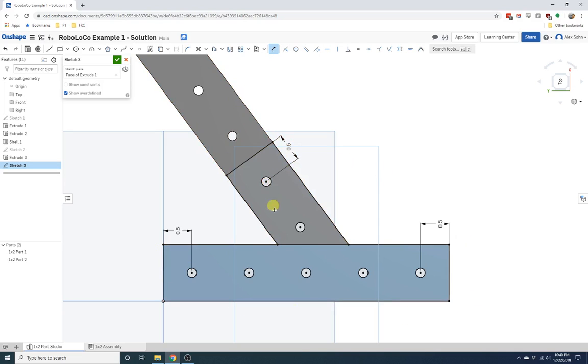So I have all the holes defined that I want to attach everything, and I have all of the bracket angles. So you'll notice that I'm just doing the outlines. I haven't put any fillets or any chamfers that I might want on this sketch yet. But everything's black, everything's defined, so we're going to extrude this.